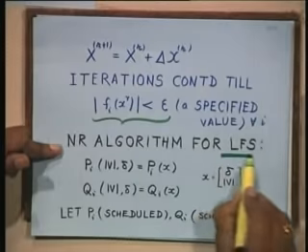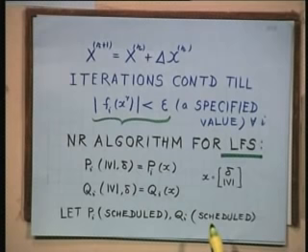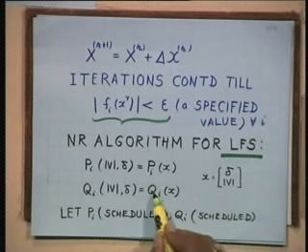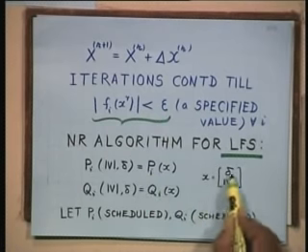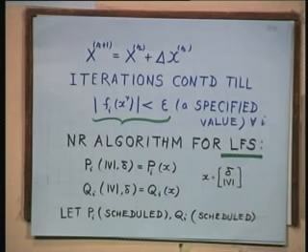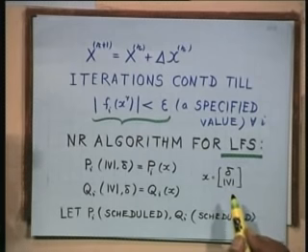In our algorithm, now we come to the proper part. So far we have been talking about mathematics. Now let us talk of electrical engineering or power systems. For load flow studies, you are aware of these two equations, Pi and Qi. These are called SLFE. Let's say this Pi is a function of x, Qi is a function of x, where x is this delta and V. Why am I doing this? I am assuming that all buses are PQ buses except one.